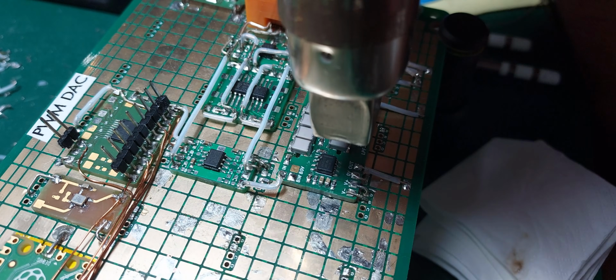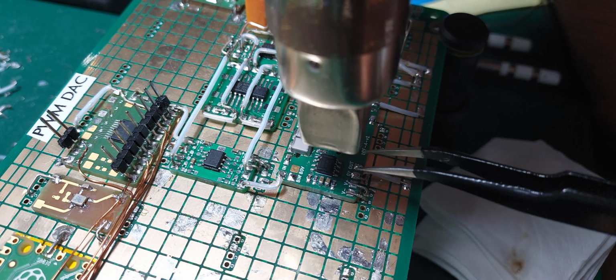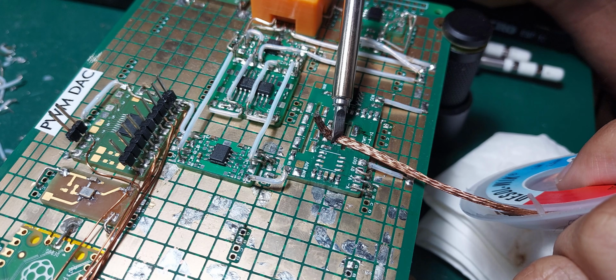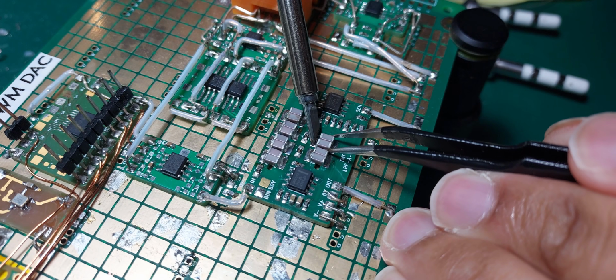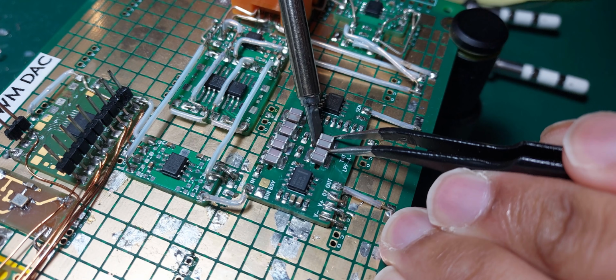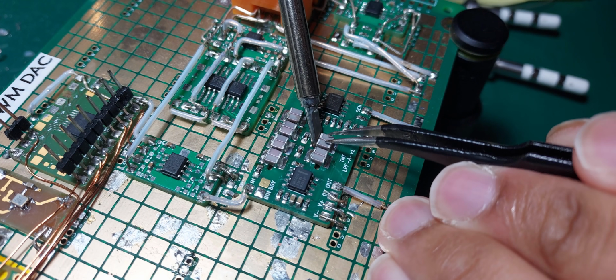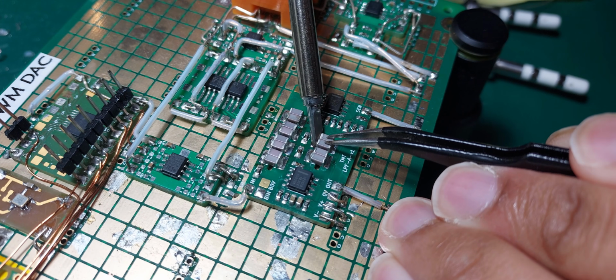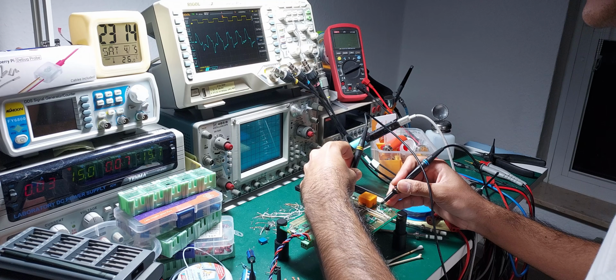Since I was not getting anywhere with the composite amplifier, I decided to desolder the capacitors and the OPA140 and replace the former with two smaller 100 nanofarad capacitors, almost equivalent to the 220 nanofarad capacitors Mark recommended, and the latter with a faster OPA828. This gave me the lowest measured ripple values yet, around 7 microvolts peak to peak, after I realized that my bad probing was having an influence on the measurements.